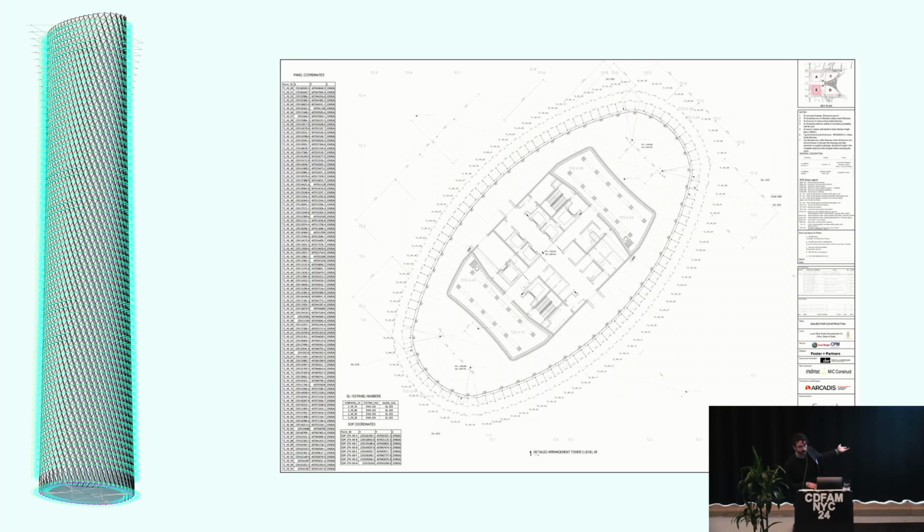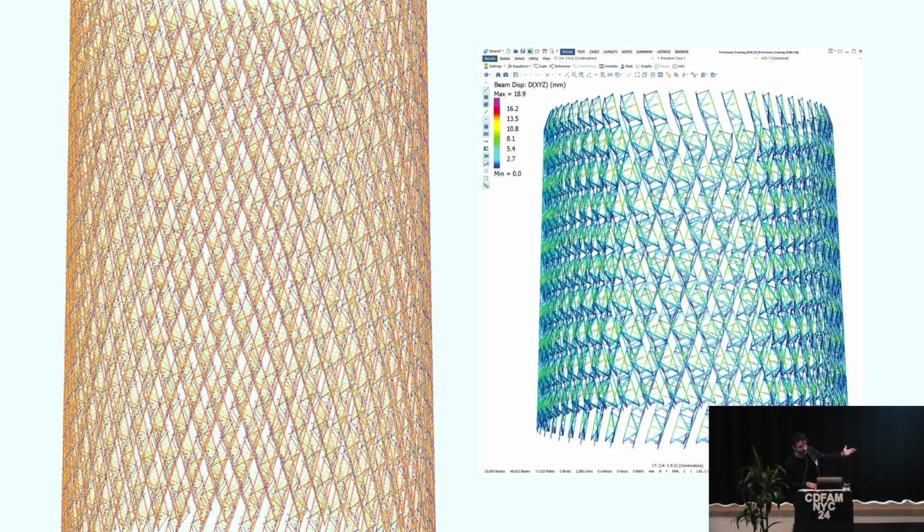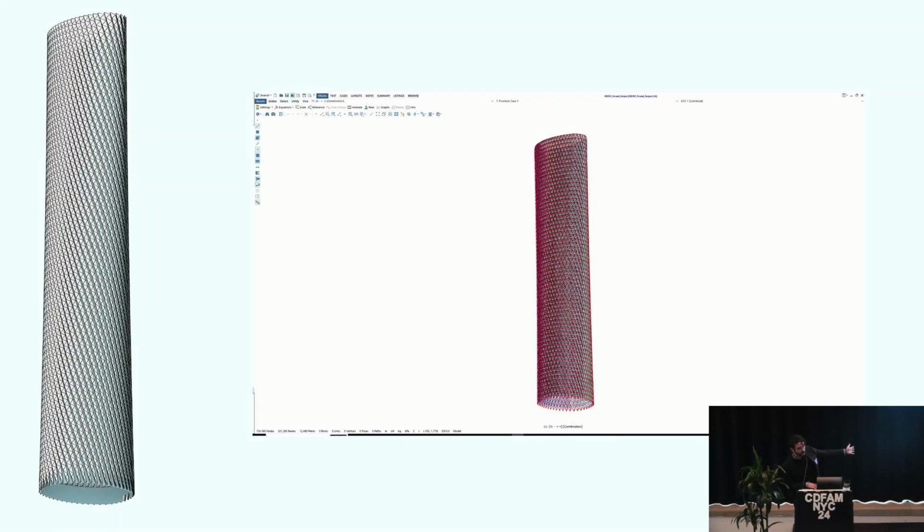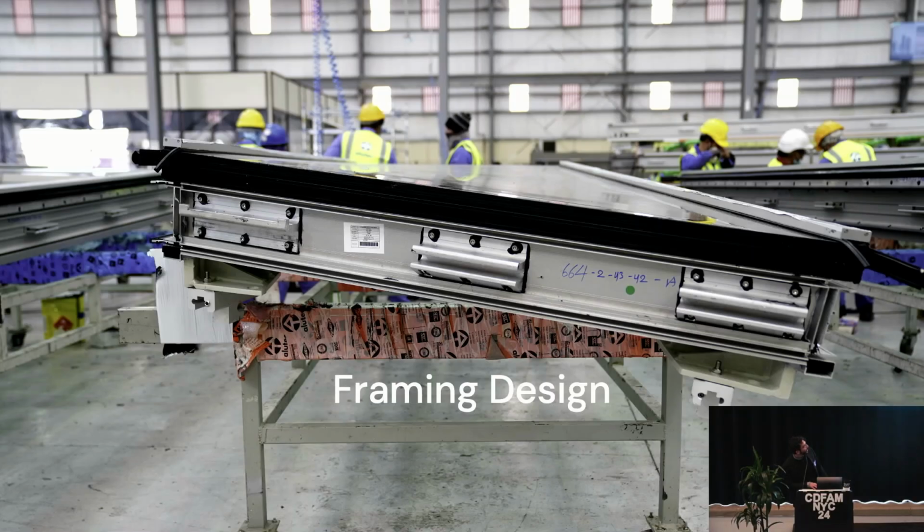If we want to make a two-dimensional drawing of where the embeds go, that's available. Here we're measuring the linear feet of every single element in the model so that they can start ordering aluminum from like the second month on in the fabrication process. Finite element simulations of like 8 floors or all floors or whatever.